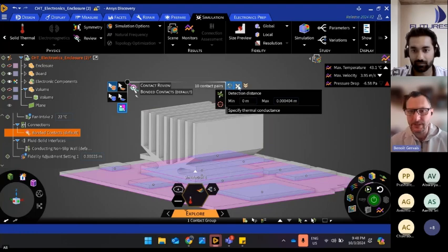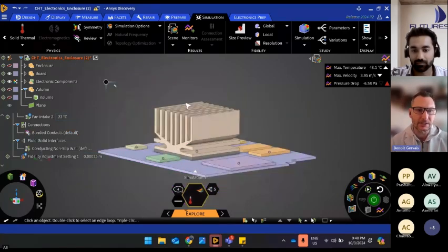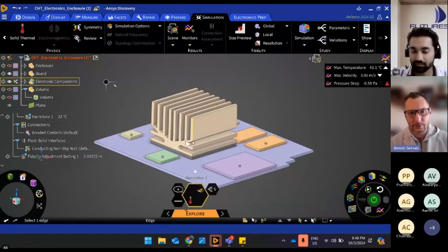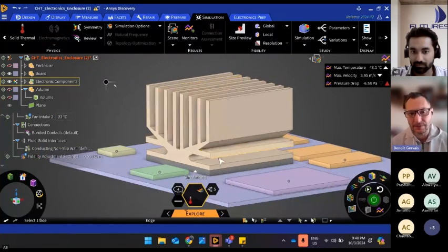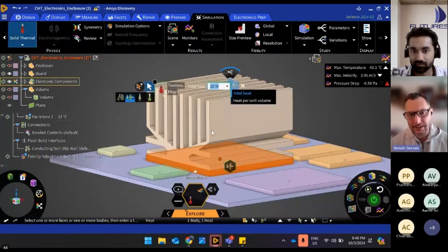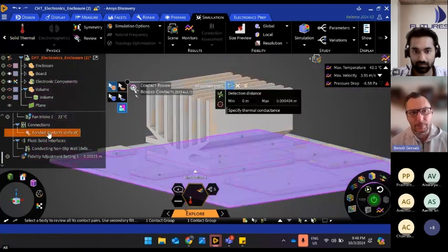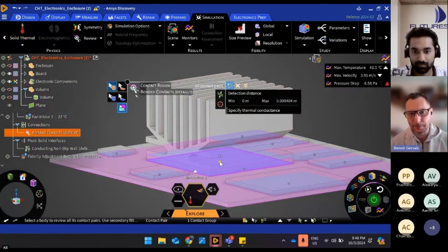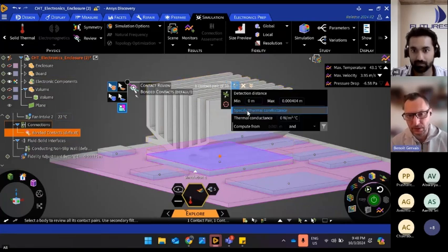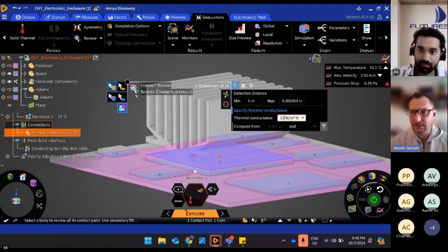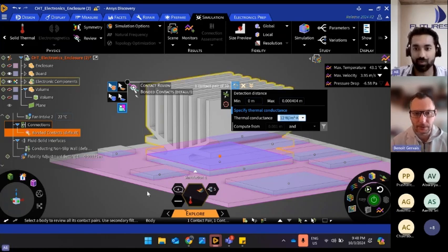Usually, what I've seen from my experience is those thermal greases or pastes or transition materials will typically have some form of specced out thermal resistance or thermal conductance, and then you can apply that to the model between the two components. So I hope that answers your question for that application. Good question. Yes, thank you so much. No problem. You're welcome.